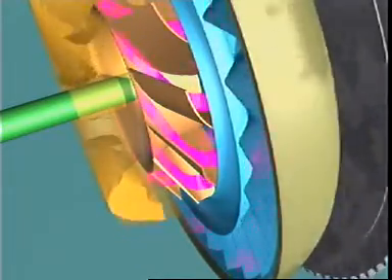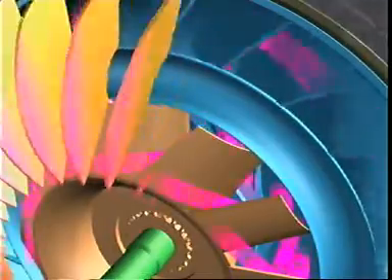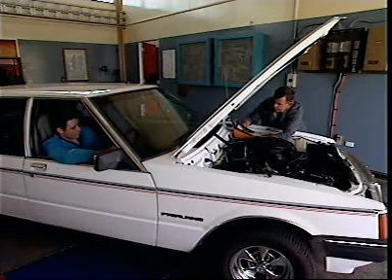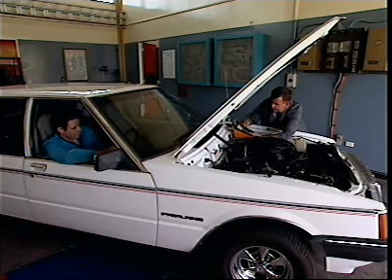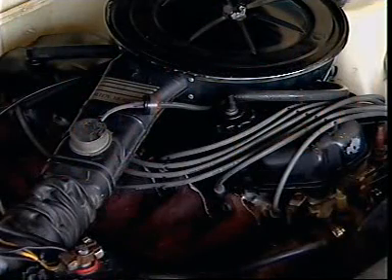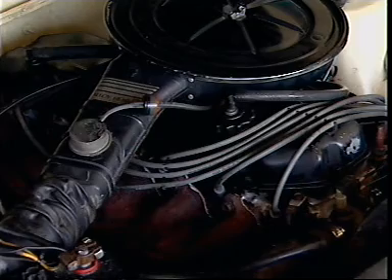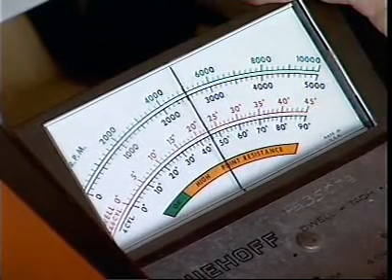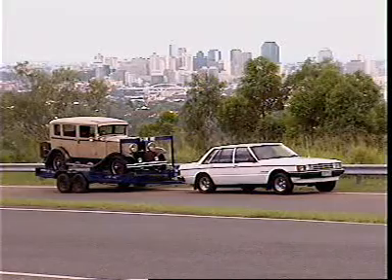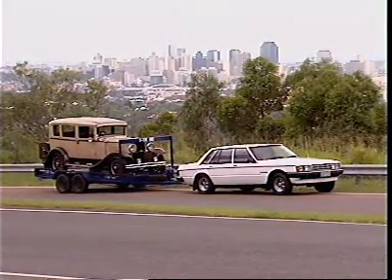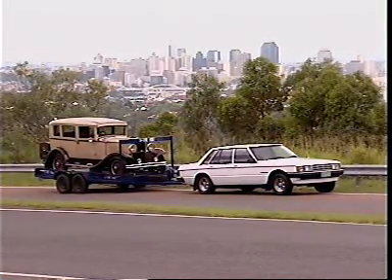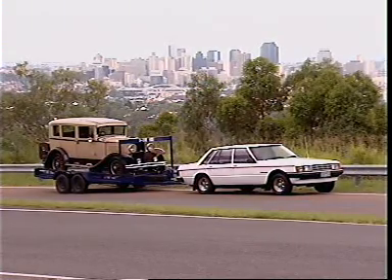Torque multiplication exists only when there is a difference in speed between the impeller and the turbine. The magnitude of torque multiplication depends on load. When the turbine is stalled, it has a maximum value of about 2.2 to 1. Stall is an operating condition where the turbine is stationary and the engine throttle is wide open, making the rotational speed of the impeller as high as possible. Stall can be approximated to when a vehicle moves from rest up an incline, towing a heavy caravan or car trailer.